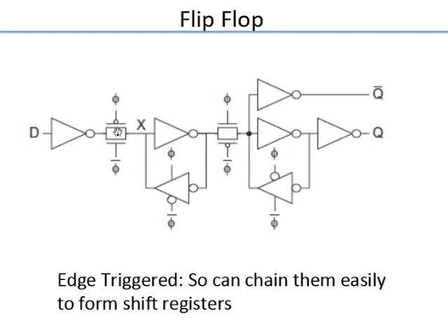So you have this master latch and the slave latch, and they operate in a ping pong fashion. When master is transparent, slave is opaque. And when the clock goes from 0 to 1, master goes to opaque, slave becomes transparent. And so the data of the master comes into the slave and goes out. So only at the rising edge of phi, basically you have the output. Now these flip-flops are kind of the workhorses of synchronous designs.